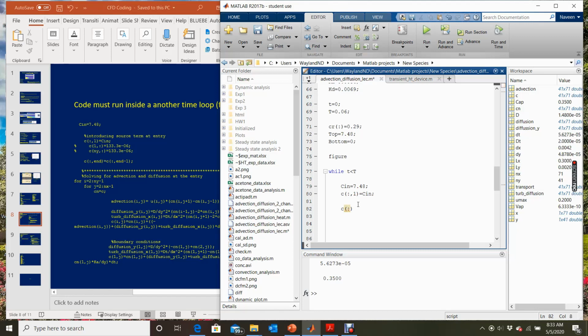Whatever is coming from the inlet and goes to the outlet must come back again to the inlet. Without that boundary condition we will not be able to get that loop kind of action in the CFD code. Otherwise it will give stationary values for everything, so the dynamic behavior will not show if we didn't apply the periodic boundary conditions. We will understand this when you code it up, so please go ahead and try different methods to clear this point.